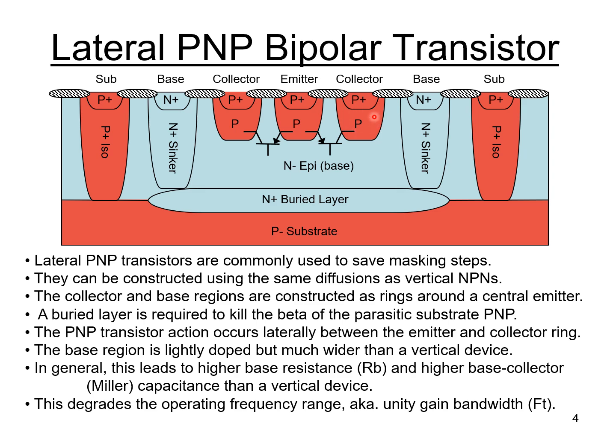I'm calling it P base: it's the P base of the vertical NPN transistor, but it's the P collector region of the lateral PNP transistor.